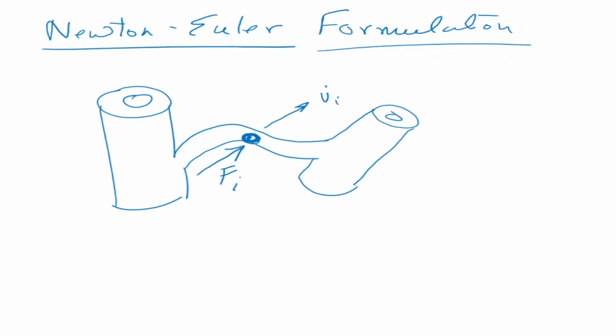So this is Newton's law: the force is equal to mass into acceleration. So the force here is equal to mass into Vc, mass into acceleration, right? For a link which is moving with a particular acceleration, we have to give a force, and this force is equal to mass into acceleration. So this is one equation which we are using. Some things to note: where is this force acting? This force is acting at the CG of the link. So this is my CG of the link. That is to be noted.